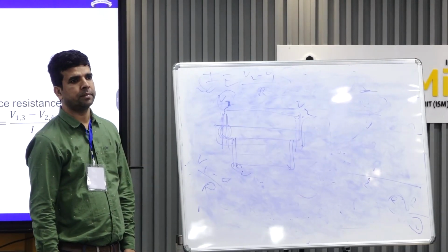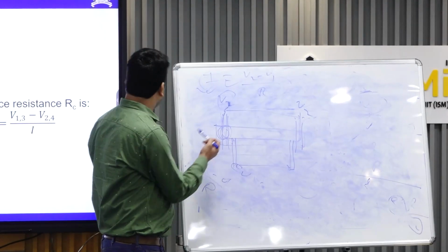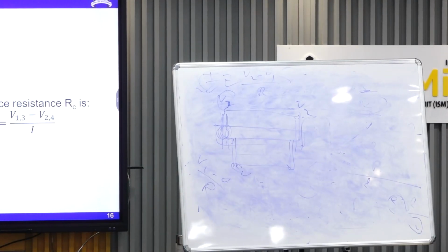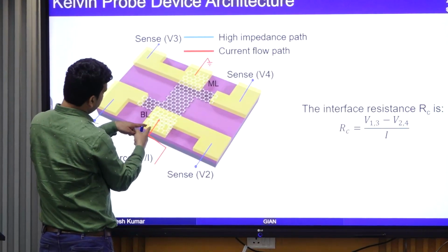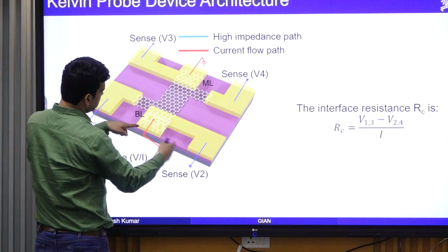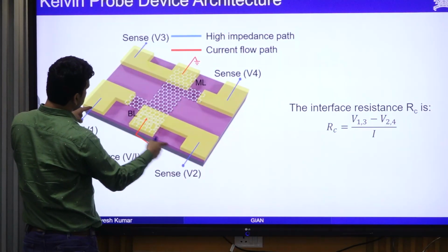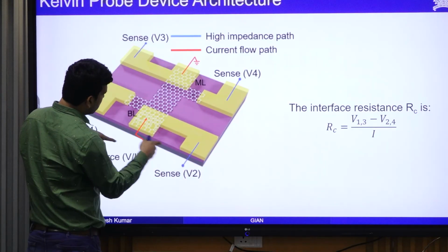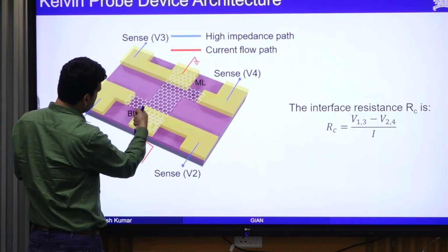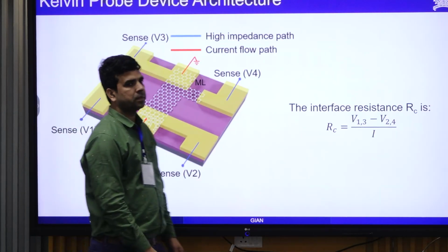Right? You are getting it or not? This will be the resistance of this contact area. Here I am forcing, I know the voltage, and I am sensing here. This contact and this contact are the same. So V2 I have sensed here, V1 I have sensed here, which is just nearby. If I take V1 minus V2 divided by I, this will give me the resistance of this local area. Understood or not?